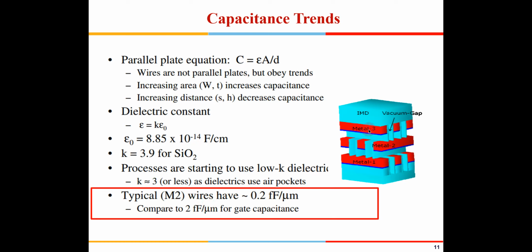Because you need electrostatic coupling between the poly and the substrate for the MOS device to work well. If there is no capacitive coupling, then channel formation will be affected. If you see the ID equation, there is one Cox which comes in: ID equals mu Cox W by L. So for greater ID, Cox has to be greater.